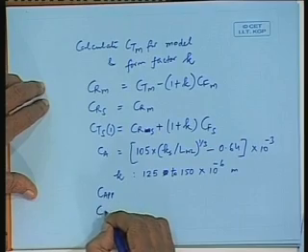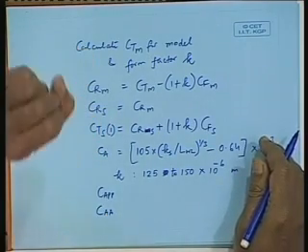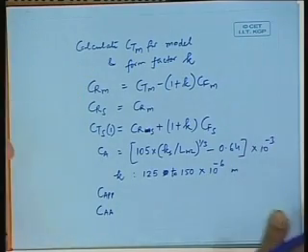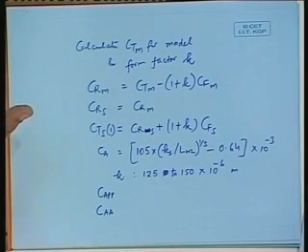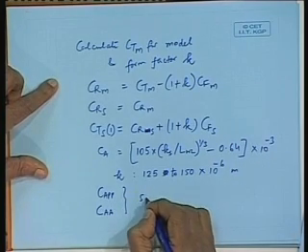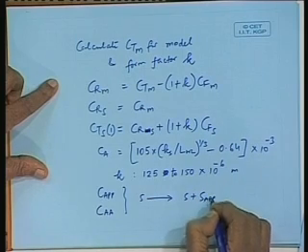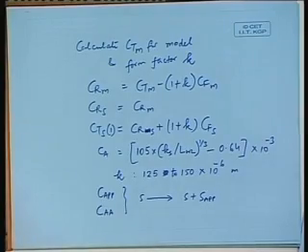And similarly, you have to have the wind resistance coefficient, CAA. Again, calculate the total wind resistance, divide by the total weighted surface, as CT is calculated, half rho S V square. That S may be changed to S plus appendage weighted surface. Then you can calculate resistance for the total ship including that of appendage weighted surface.